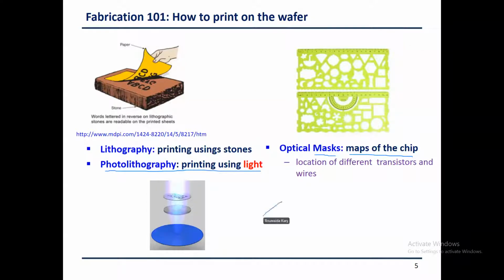Yani, it is exactly as if I decide that in this location on the wafer I'm going to implant a drain, or ions to represent the drain, by showering them at this specific location. So mask 1 will have an opening in this specific location.